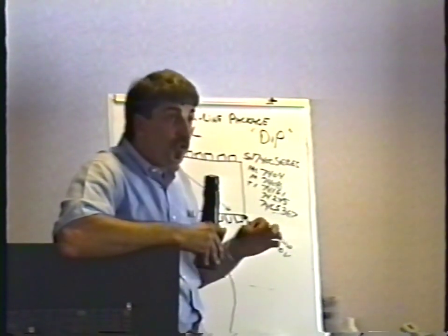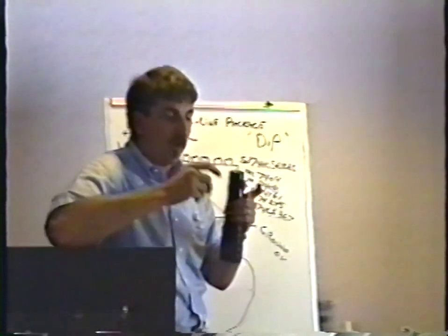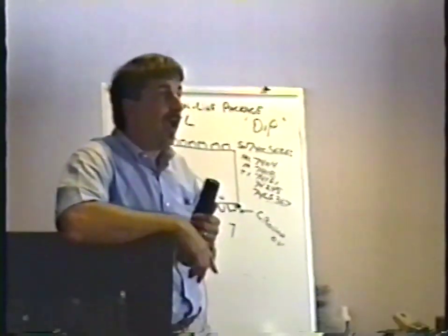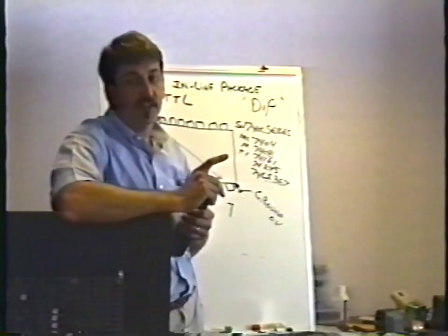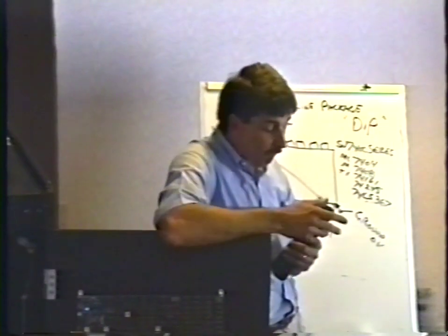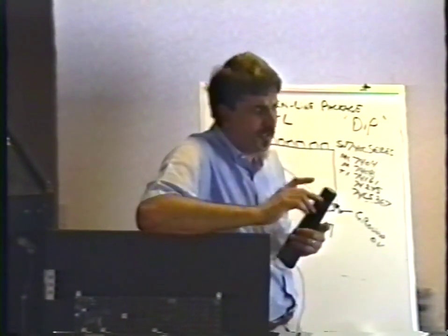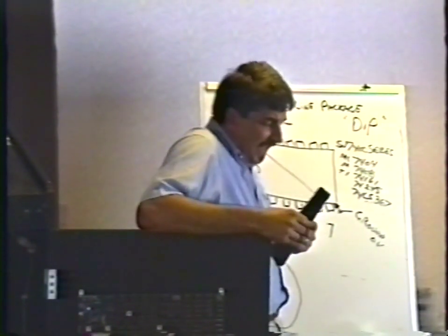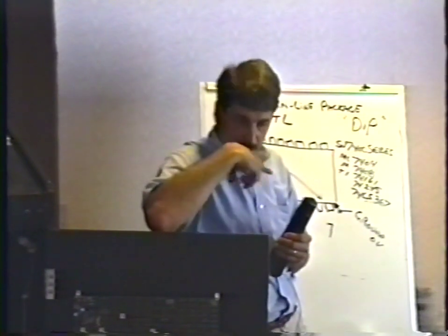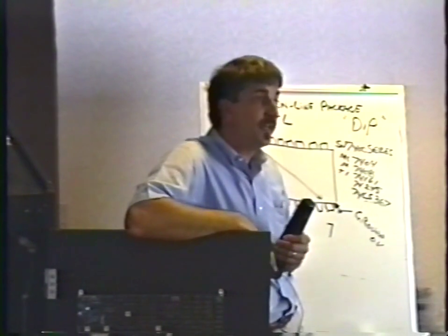Another thing that you can do is to get another one of the same game and try swapping all the chips that are in sockets. I always tell my boss, never get just one of anything. Never get one of any game. Because if you only have one, I can't do that anymore. But for instance, we had an Outrun problem. We just saw garbage on the screen, like this garbage, almost exactly the same. But it did pass the whole ROM check. I don't know how or why, but it did.